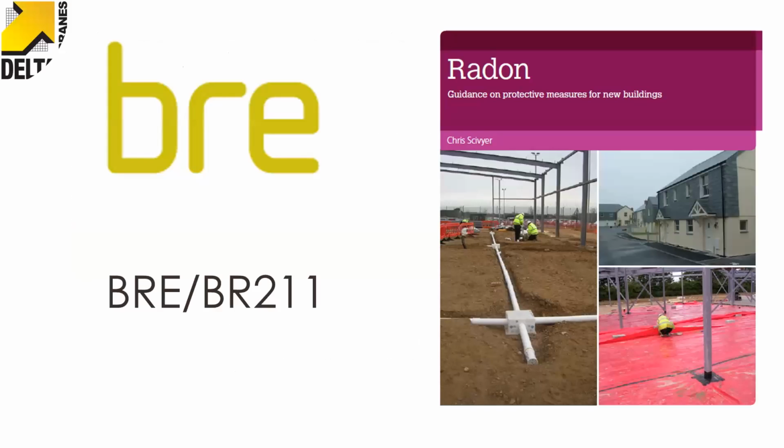And BRE 211, which is the go-to radon standard. I need to factor that in as well. If it's in, you know, Cornwall or Aberdeenshire or the Peak District or somewhere like that, which is perceived as a radon affected area, we need to design in either basic radon protection or full radon protection. This isn't a radon seminar, so I won't go into what the differences are, etc. But it impacts on the waterproofing system, okay?